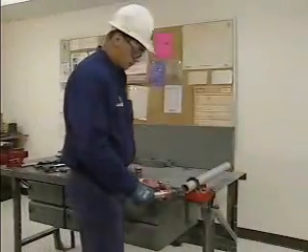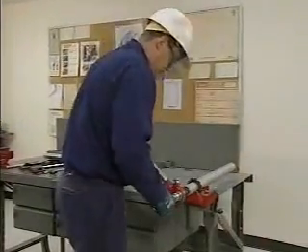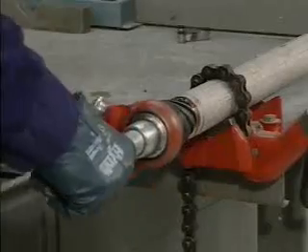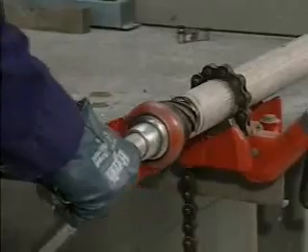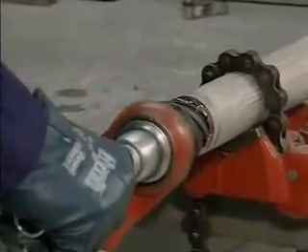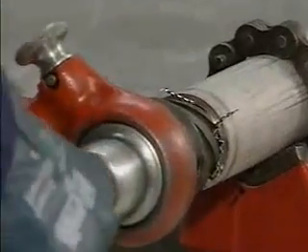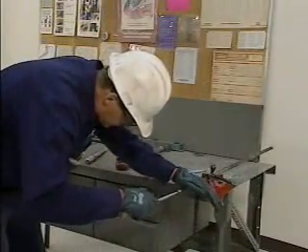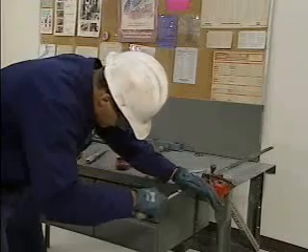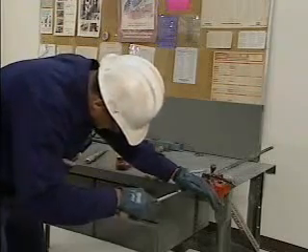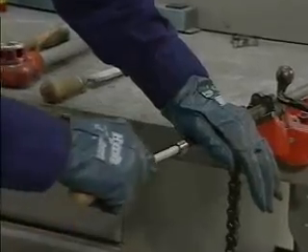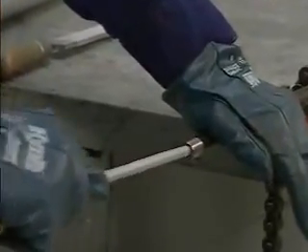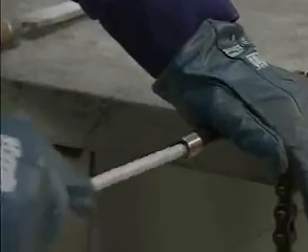Insert the reamer or file into the pipe enough to exert a slight pressure without damaging the pipe wall, and rotate the reamer or file inside the pipe until the pipe surface is smooth and free from burrs and ridges. A rat-tail file should be used as a last resort when a reamer or a half-round file will not fit inside the pipe. Rat-tail files can leave marks on the inside wall of the pipe, which makes the pipe wall thin and susceptible to early failure.